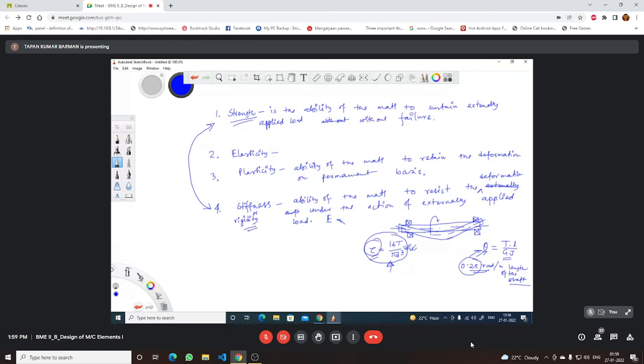Functional failure. Stiffness, you can see the deflection. Basically, when you are using one machine of this type, there should be some permissible level of deflection. In your engineering mechanics, you know how to calculate the deflection when the loadings and values are known to you. You need to calculate the deflection value, and then only you can say whether your design is safe enough considering the lateral rigidity or lateral deflection. So definitely you are getting the flavor of design right now. Definitely we will design the component under these situations.